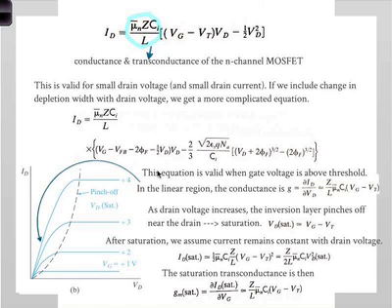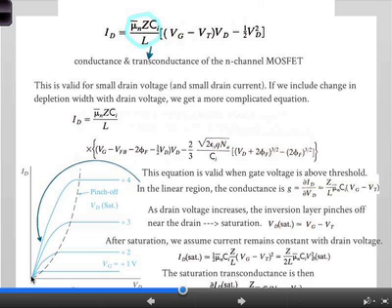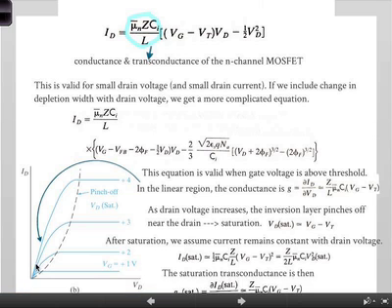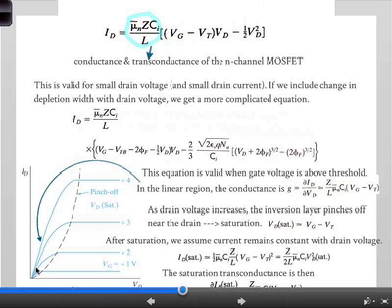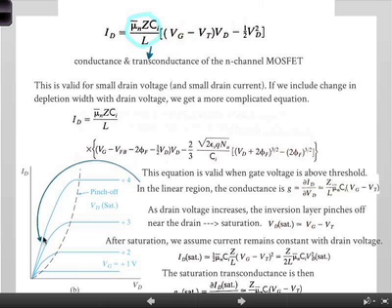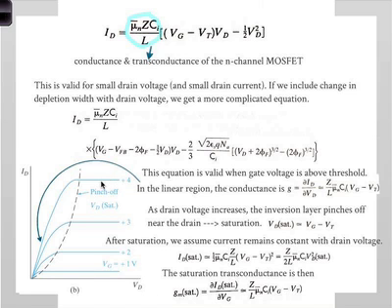If you look at the curves here, this is linear when the drain current and the voltage are very small. At some point, the quadratic part comes into play, and here you get a bit more of this part of it. And at some point it saturates. So just understand the physics rather than the equations so much.